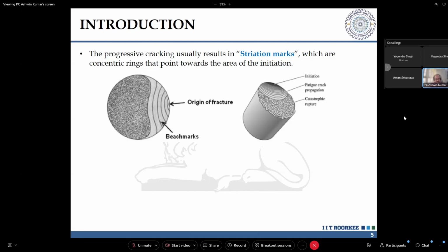When I say a ductile material, when I look at the fractured surface after it has been tested under a monotonic test, our teachers say there will be a dimple mark, which signifies ductile failure. But in fatigue failure, the fractured surface will look exactly like this. You have certain beach marks that point to the origin of the fracture. Here is where the fracture originates, and then you have these beach marks or striations like concentric rings, which show the propagation of the failure surface.